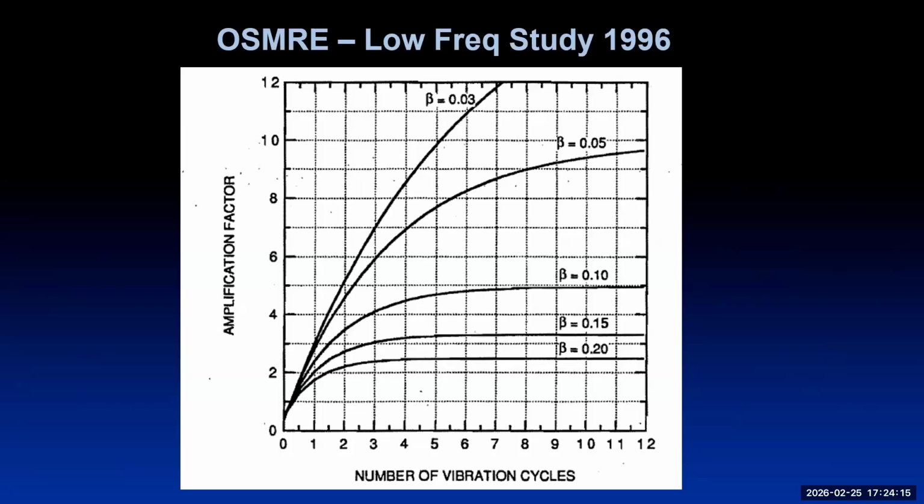But now the question is, does it increase? Does it have a 3-part curve? Well, the 3-part curve says that it races up dependent on the amount of material which is participating. If there isn't very much, it doesn't go up very much. So for minarets and chimneys, that damping stays around 0.5%.